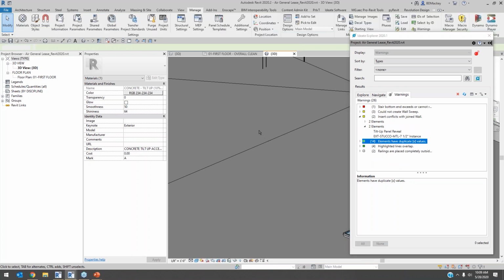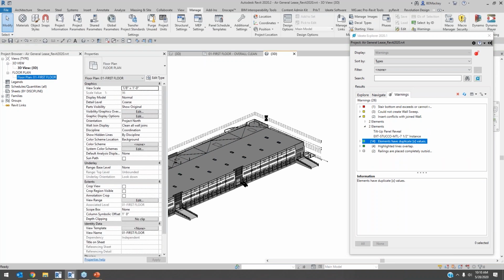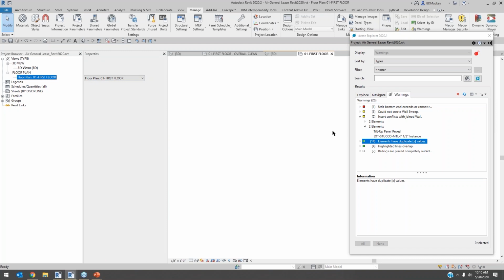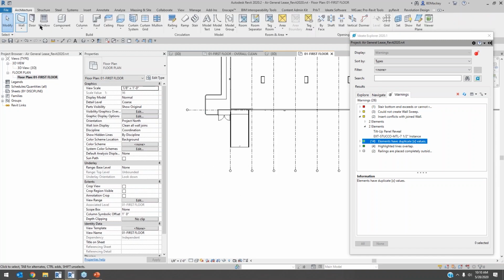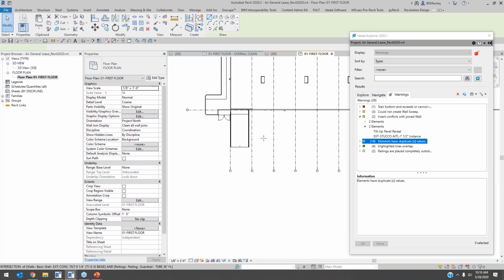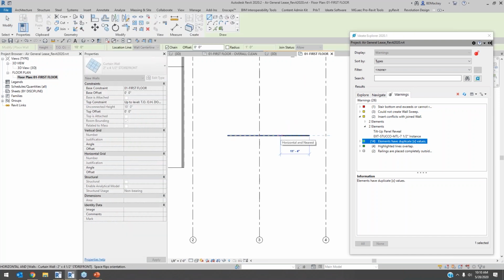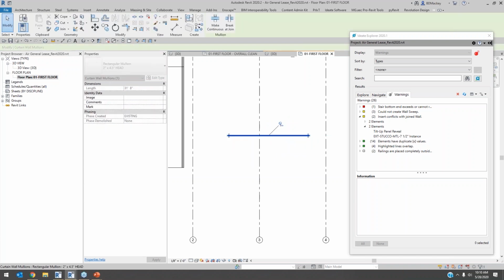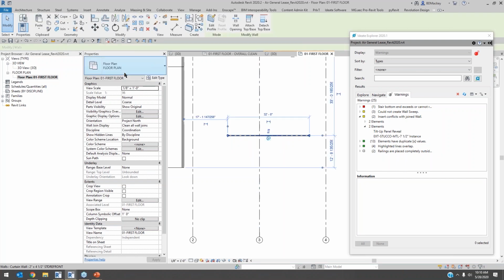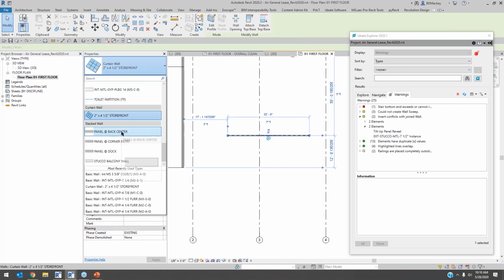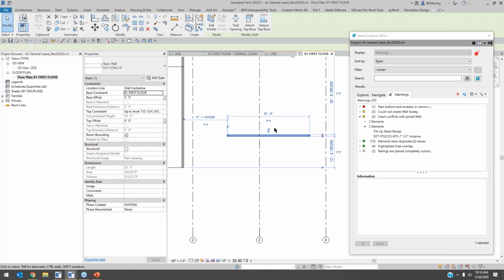So the other thing is I'm gonna go to a floor plan on this one. Sure, here's a floor plan. There are some warnings in Revit that when you get inside of here, and I'm gonna go draw a couple walls, architectural wall. I'm gonna draw one like this. Probably a curtain wall, right? Yeah, I did not want a curtain wall, so let me go swap that out. Let me grab the wall, not the mullion. So I'm gonna come in here, I'm gonna draw a wall, not a stacked wall, I'm just gonna draw a normal, sure, concrete 8-inch wall, right?